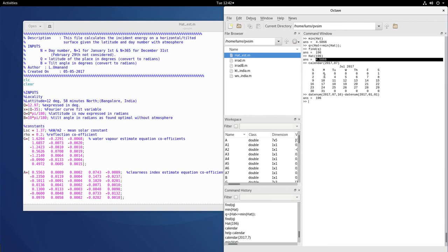Now that is the crucial and important value that you have to take away from this, and you have to design your PV panel to deliver the full load requirement even during this least insolation day. Then any other day in the year is covered.